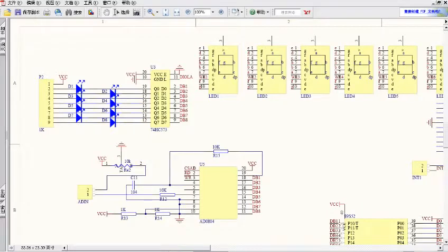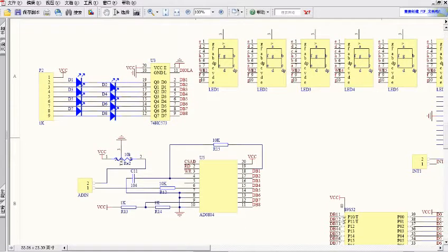Obviously this is a closed loop as well, and then we can light up the first LED. Okay, now that's the electrical working principle. It looks pretty simple. Just a voltage source and drive this LED with a current limitation resistor, 1 kilo ohm.